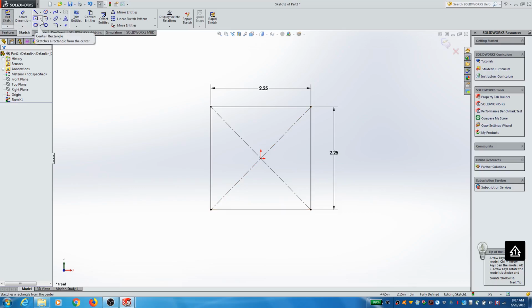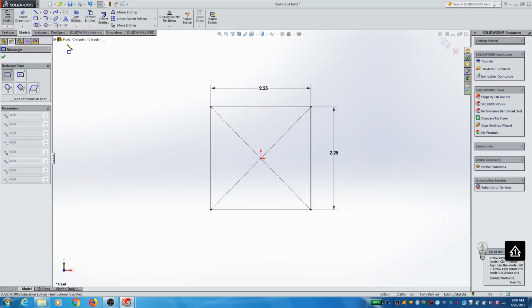And I'm going to use a different, notice how I used a center out rectangle, and I centered it on the middle of my space. The middle of my space is marked with these little red arrows, okay? We call that the origin. So depending on what math everybody is in, if you're maybe a junior or a senior, you might have seen something called an origin before. If you're just beginning, don't worry about it. It's called an origin, all right? So I selected this to create this first square. I am going to use a different rectangle tool, the corner rectangle tool, to create another block.